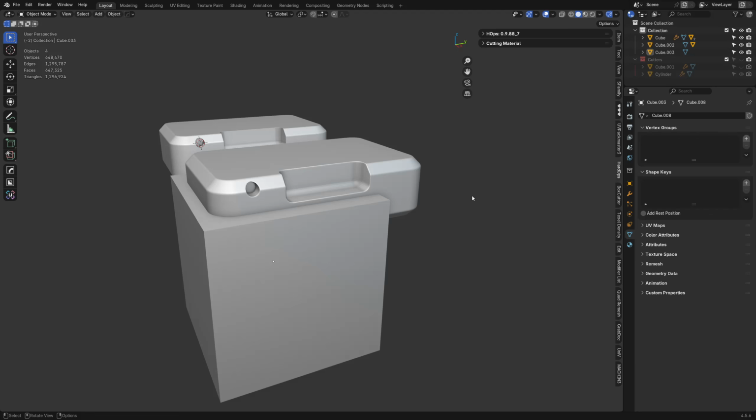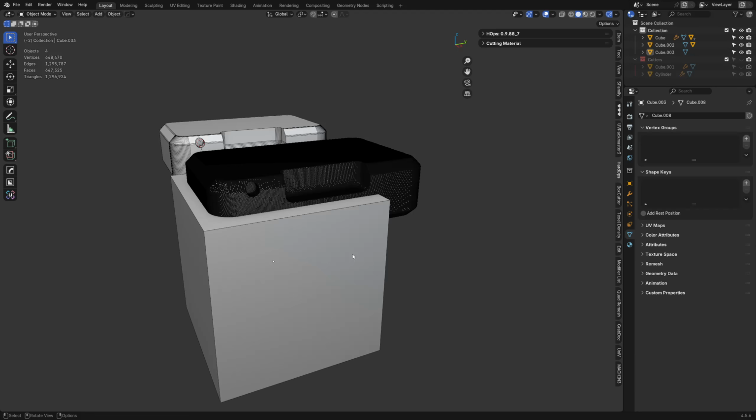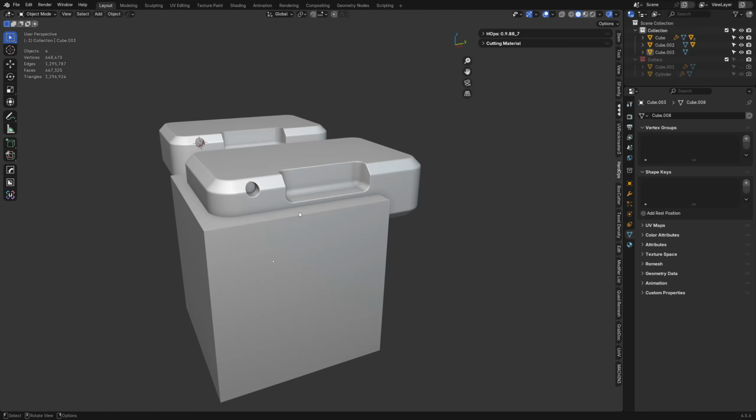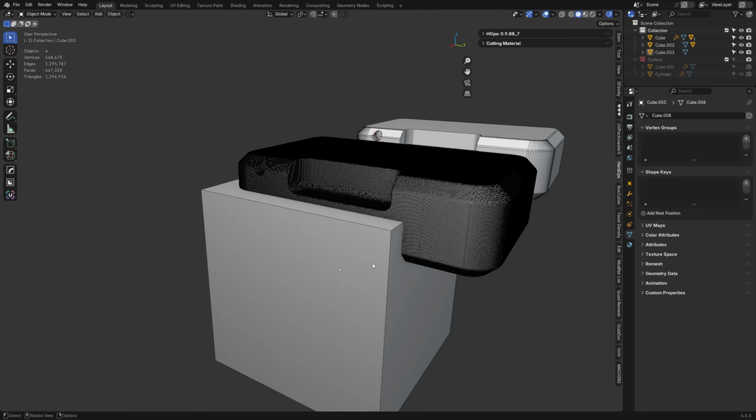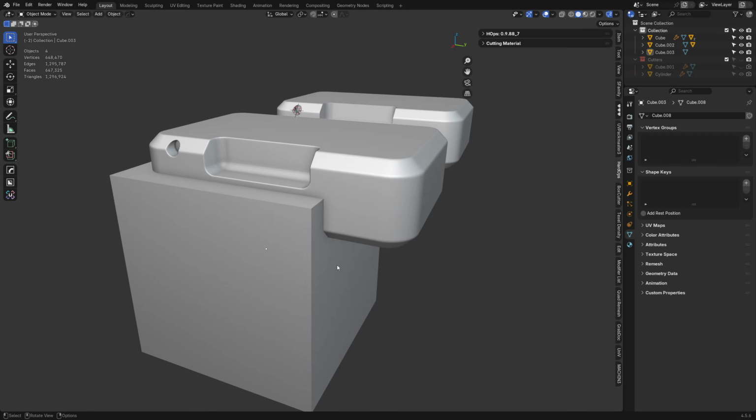Now, the reason why it's so useful is the same reason they added it to the trim tool inside of Blender, right? It's because it doesn't fight with the wireframes lining up with each other as much. Like we were seeing earlier, where it kind of collapses that bevel down. Sometimes that would cause Boolean errors as well, where the mesh disappears. It doesn't really do that. So this is a lot better for design anyway. This is all I was trying to point out here.